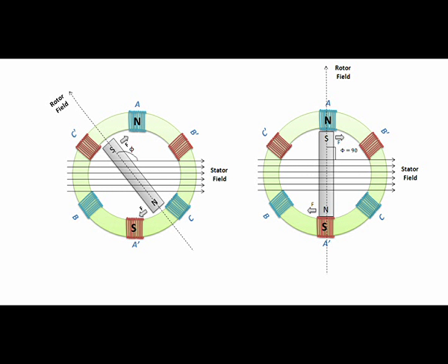The major advantage of FOC over other methods is that the rotor is monitored at every position and the algorithm ensures that the rotor magnetic field and stator magnetic field are always aligned at 90 degrees to each other. As a result, the torque or the tangential force is at its maximum. In order to achieve this, the precise real-time position information of the rotor is needed.